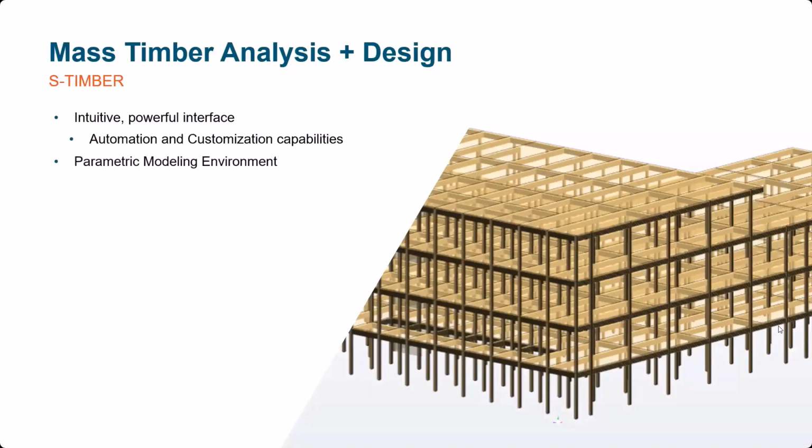It also offers a parametric modeling environment, and some aspects of that that are relevant to timber design would be the generation of rigid offsets when you have large section sizes of members that are connected at their center line, for example. It may also involve the creation of different types of objects that are collectively defined or grouped together from different smaller components, like a shear wall or a floor diaphragm that might have a number of different elements within it that can be defined and edited parametrically.